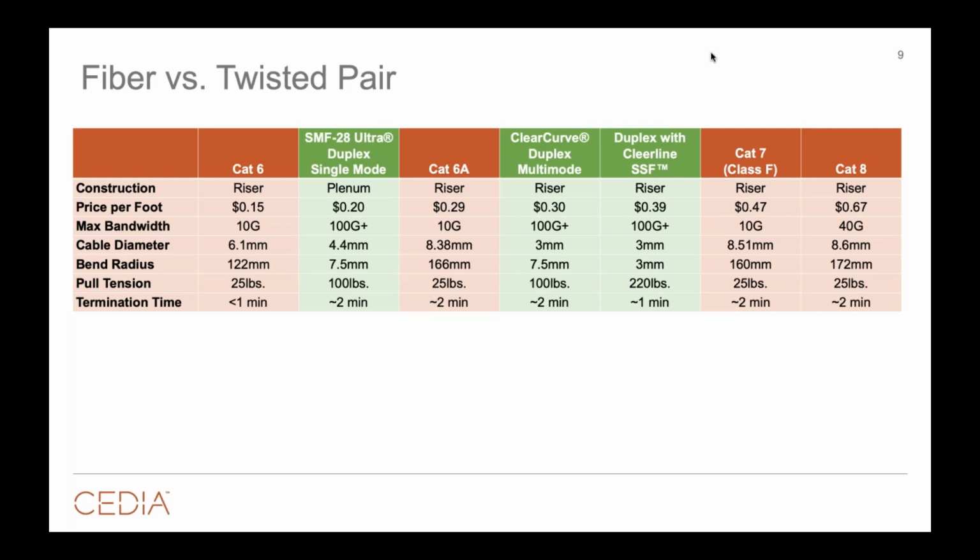It is a superior way to cable installations if you think through the issue of power. You can't run power over fiber. You need to make sure that you're powering the boxes that plug into the fiber optic cable on both ends. Sometimes powering means you plug it into the USB port of the display. Sometimes powering means, look, you got to have an electrician drop power out at the gate or at the security camera or whatever it may be. But beyond the power conversation, fiber outperforms in just about every other way.